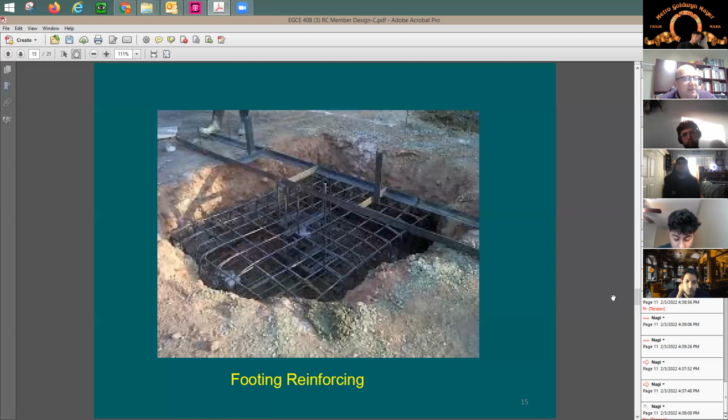So instead of having it be 2 feet, I'm going to make it 2 feet and 6 inches. Instead of 6 feet, I'm going to make it 6 feet and 3/4 inches. I'm adding a few inches right and left, so I'm giving you a slightly larger concrete footing, because I know the soil side is not really straight. It's going to be expensive to spend the time to make it straight. And don't forget, at the end, the whole thing here is going to be covered.